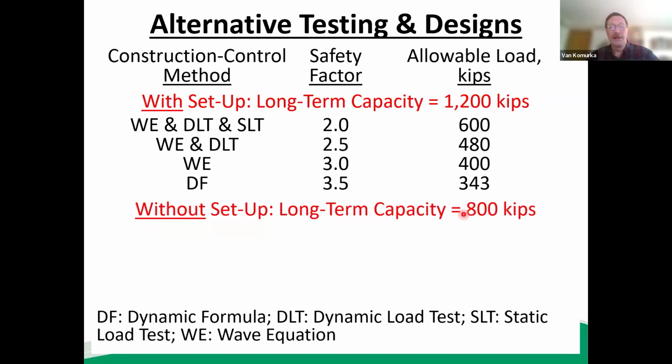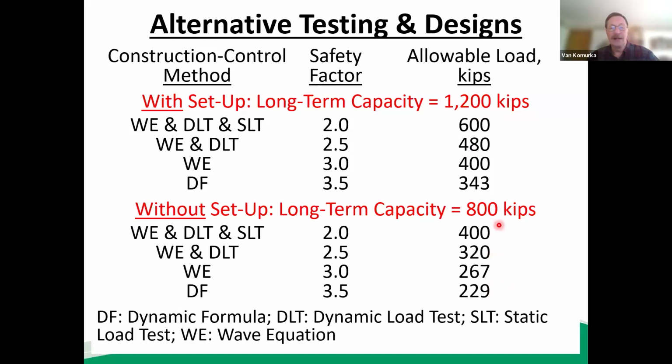Similarly, if we don't incorporate setup, we only start with 800 kips, not 1,200. And so we get these allowable loads for the same range of safety factors.